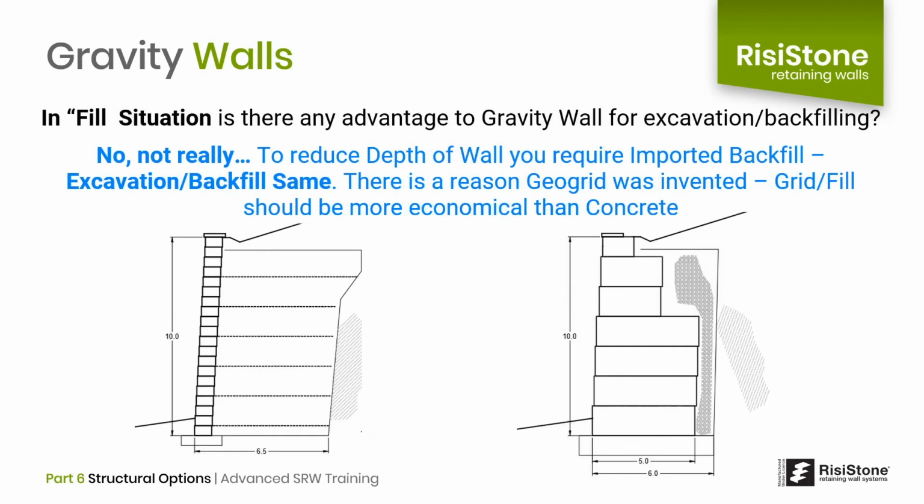In a fill situation, is there any advantage to a gravity wall with respect to excavation and backfilling? As we discussed, if the retained soil is the same for both, the overall depth of wall will be similar, and generally a grid wall should be more economical than a gravity wall. There is a reason geogrid was invented.